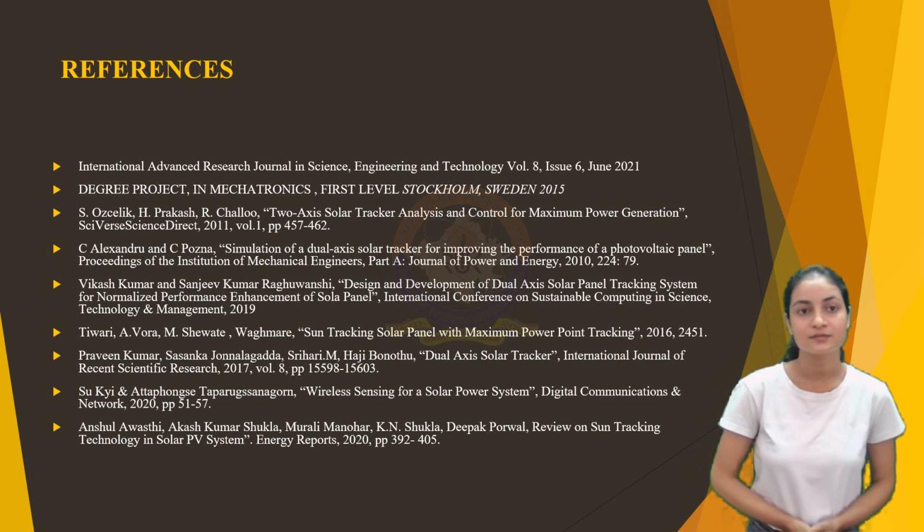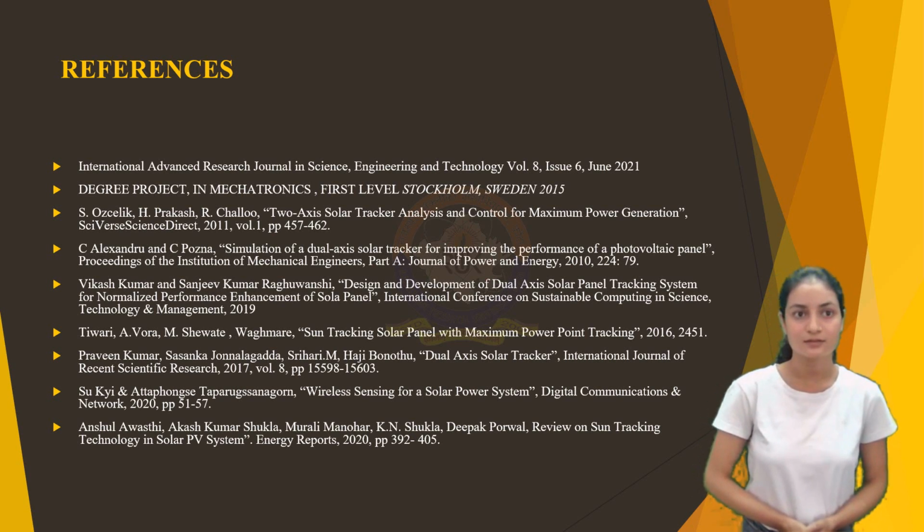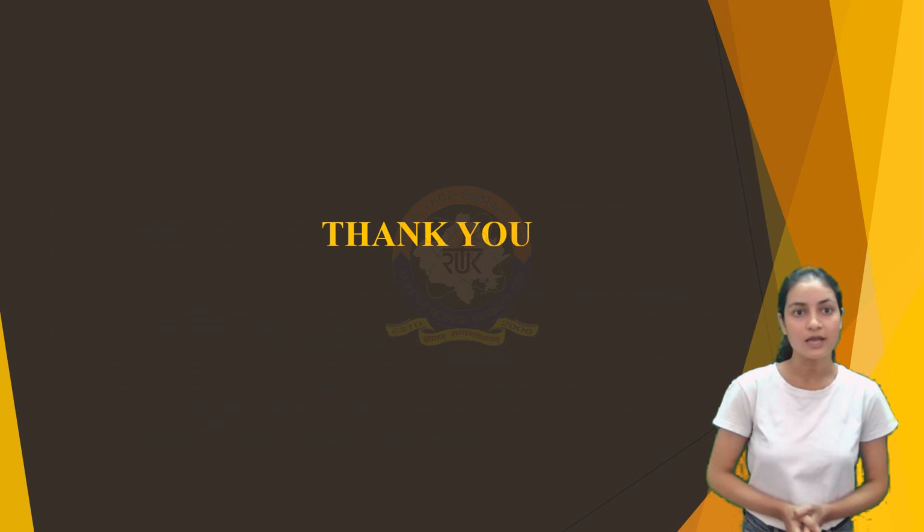Why are monocrystalline solar panels used here? Why not polycrystalline? Because monocrystalline solar panels are more efficient and have greater advantages than polycrystalline solar panels, as monocrystalline are space efficient, have a long lifespan and are better in low light.